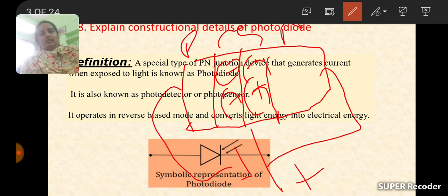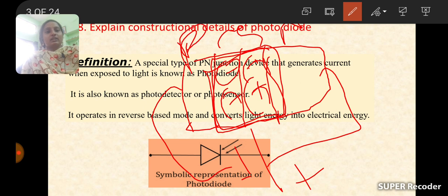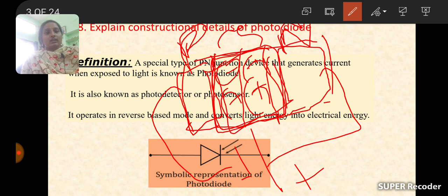So in this way, this barrier acts like a dielectric medium, and the p-type semiconductor acts like one of the electrodes and the n-type is the other electrode. So finally these two are the electrodes and the dielectric material separates these two electrodes. Finally, it acts like a capacitor. The varactor diode means simply the diode under reverse biasing condition acts like a variable capacitor. Why is it not just a capacitor?